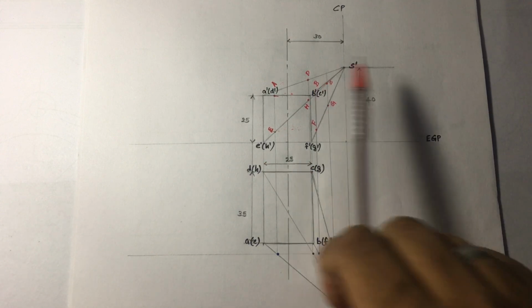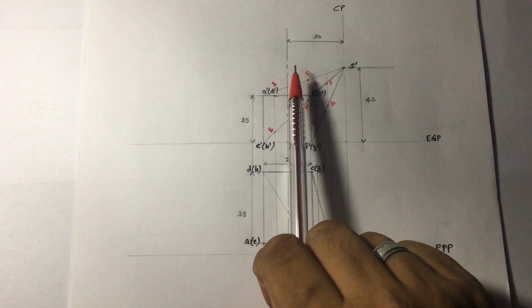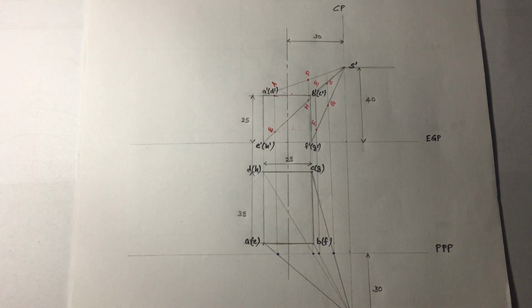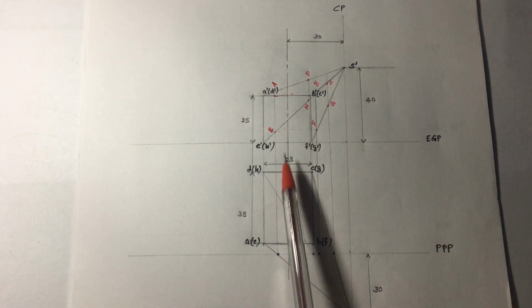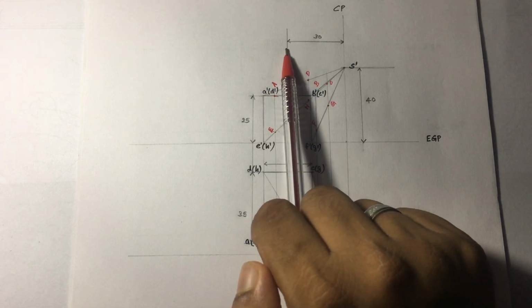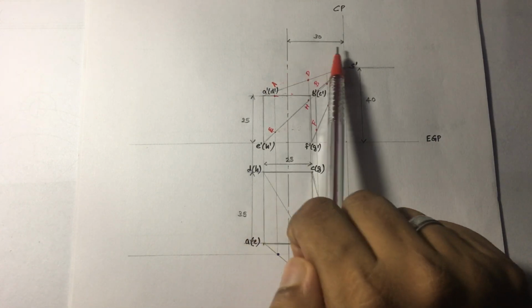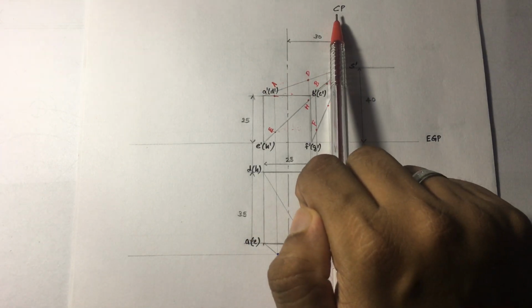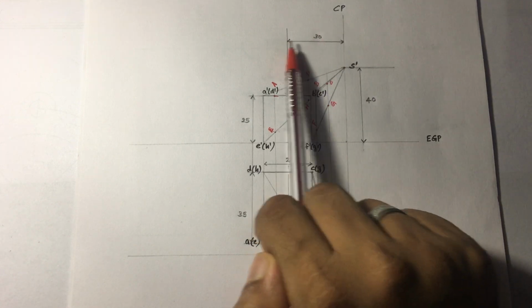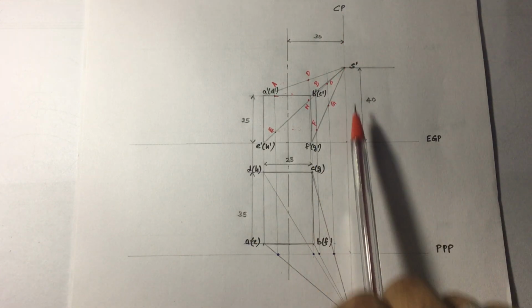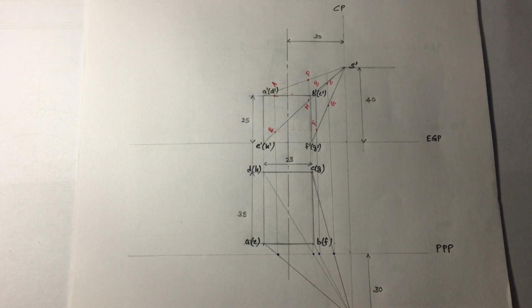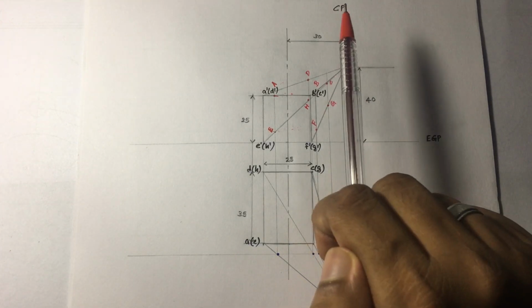And then you have to mark the central plane. In the question it is stated that the central plane is 30 mm away from the axis of the prism. So this is the axis of the prism. You have to mark it by using a chain line, and then you have to take 30 mm. You have to mark the dimension 30 mm, and you have to name the line as CP. Okay, after taking 30 mm, you have to draw a vertical line. While you are drawing the vertical line, ensure that it is completely 90 degrees. Okay, and then you have to name it as CP.